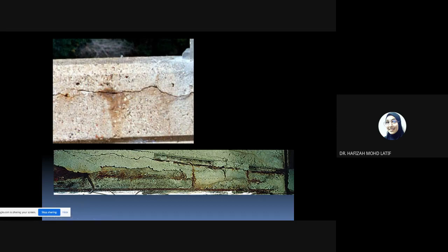That's why when you learn in semester 1, we always say you have to put the spacer bar. You remember? Not spacer bar, sorry. You put that thing, the white thing, at the construction site. Here they call it spacer block, the white one, so that your concrete cover is raised up. So when you pour concrete, your reinforcement bar will sit in the middle.